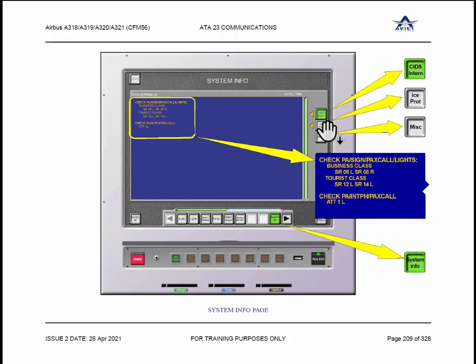So it gives you very precise, very accurate information for maintenance. Because at every power up, the system is checking all the interfaces connected to the director through the DUA, DUB, whatever it is. And if it does not get the right answer, it will mention it as a failure. So this page is good for you when you do maintenance and want to detect a failure. You can see it here on the system information page.